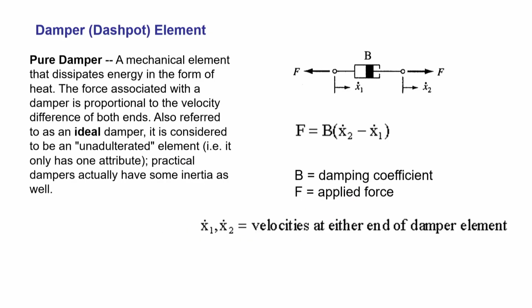Now, just like the springs, we can also have dashpots. Why do we need a dashpot? Because if there is a relative velocity between the two ends, I may want this relative velocity to be controlled, so that it does not come like a shock load on the other adjoining systems. So with this dashpot, if suddenly a force comes at a very high rate from one side, it moves this entire system much more slowly, so the load is transferred, but at a much slower rate, so that ultimately the energy gets dissipated inside the damper itself.